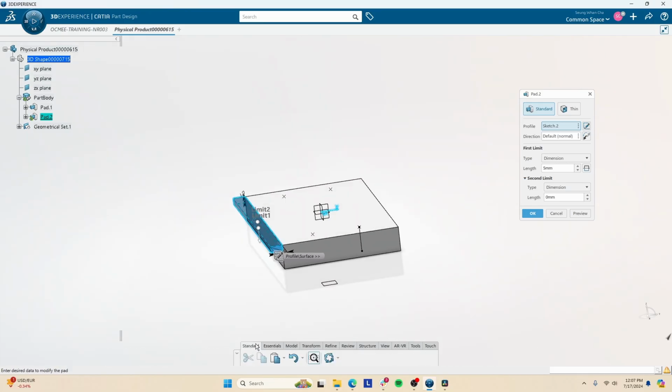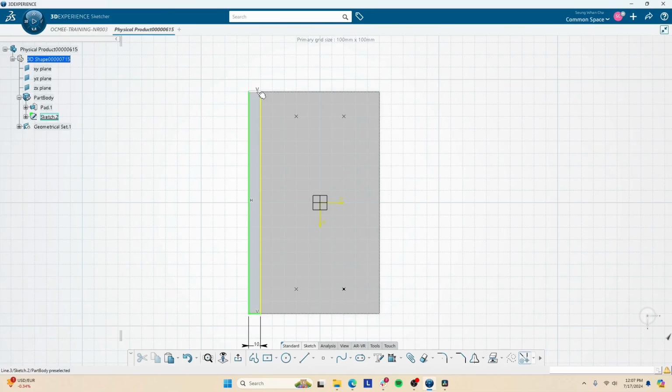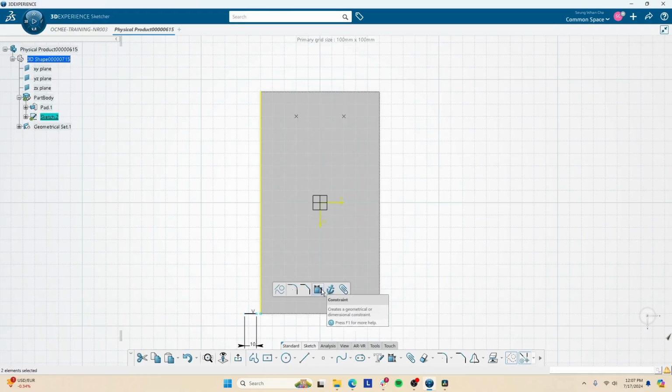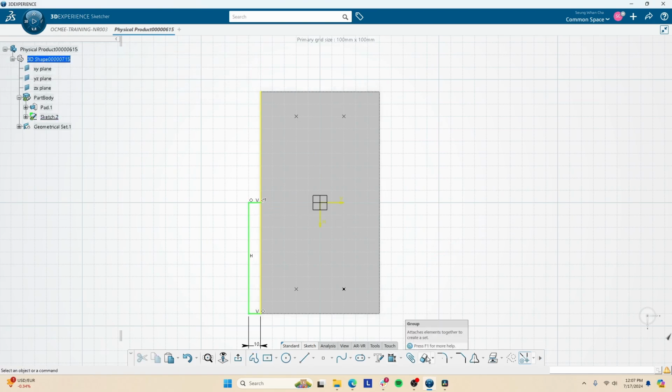Or actually, let me do this. I'm gonna go back and change it. I might skip. Cancel. I'm gonna project the same face, but come back to it a bit more. Constraint. It's just a portion of it. And what we can do is trim this out. Where is my trimming tool? Should be here, quick trim.